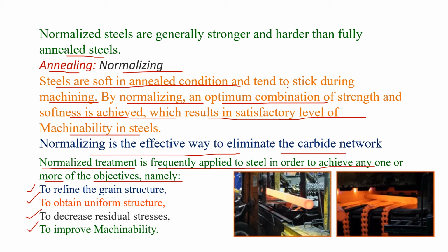While in annealing, the residual stresses, or internal stresses which were developed in the structure, can be relieved, with normalizing we can improve the microstructure as well. Just as we have studied the microstructure, we compare the microstructure of normalized and annealed metal. The normalized microstructure is a fine lamellar structure, while the annealed is a coarse lamellar structure.